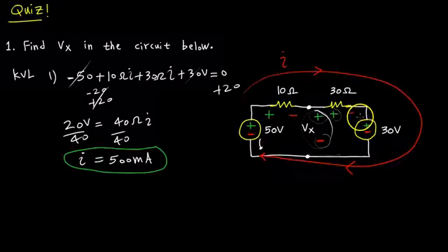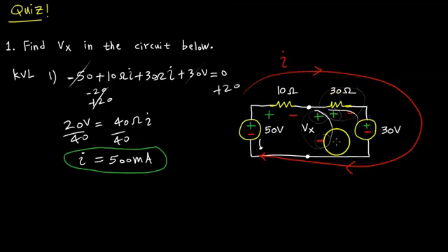But again, I'm going to keep going, and I'm going to see whatever this voltage is here, a rise here, because I'm going minus plus, minus plus. So I'm rising twice with different amounts. And do note that I have a positive current, so my assumption was correct. And the voltage drops are indeed in the manner that I've shown, and the current direction is clockwise.